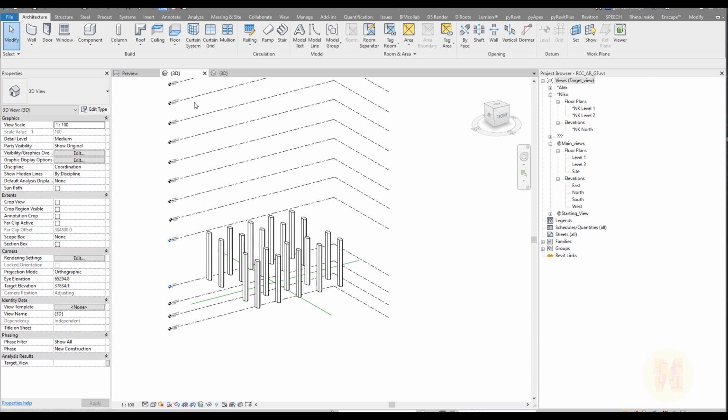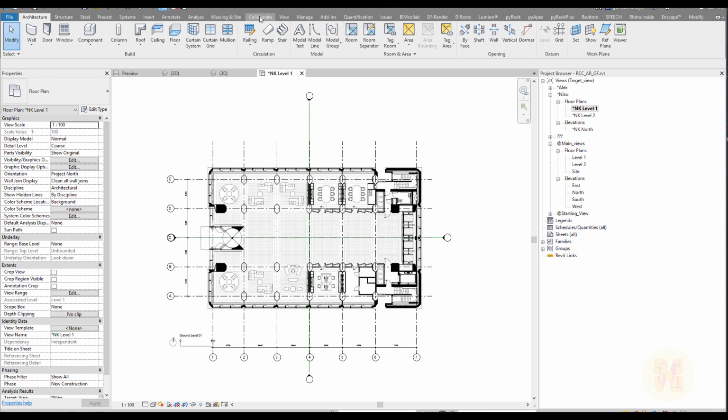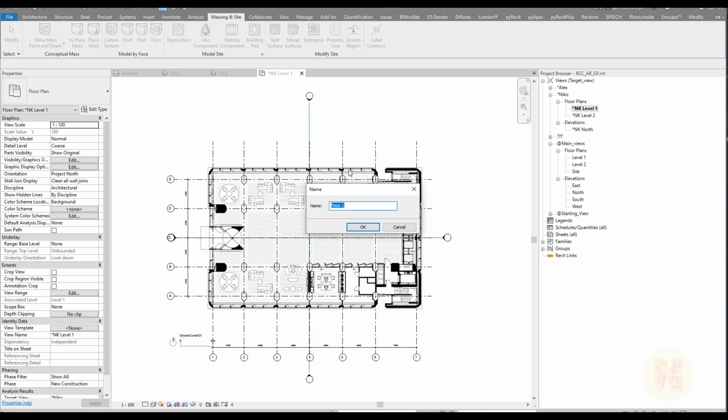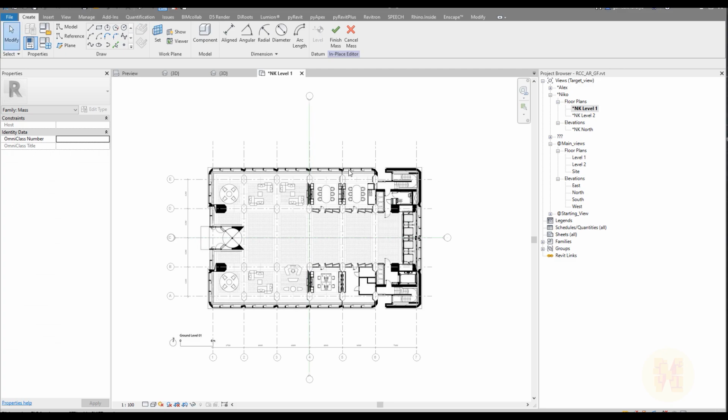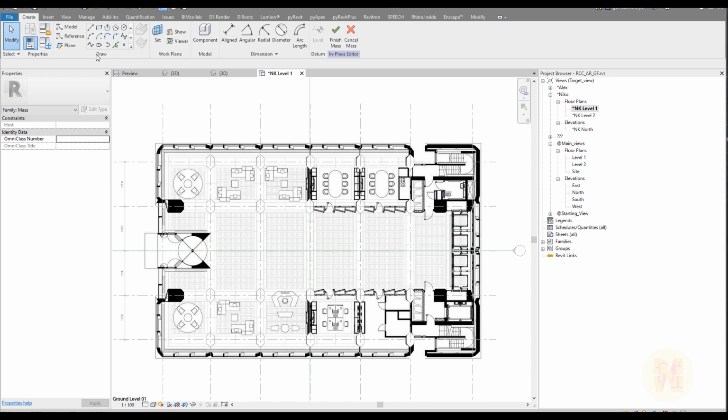So here we are, and what we're going to do next is go to the floor and start to create our mesh form. First of all, you should switch on the form, and after that you should start to create the mesh in place. Call it external, since even the facade cannot be internal, but sometimes it can be. Okay, so we have our naming correct, and here's our mesh form, and I'm starting to create it.